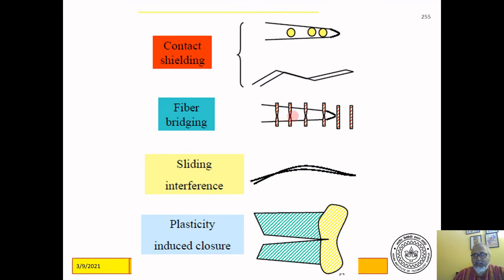If there are many of them all around, when a crack propagates, it has these fibers bridging the two crack surfaces, and thereby these crack surfaces are not exactly traction free surfaces. If you remove the fibers and draw the free body diagram, you have cracks with closing forces applied on them due to the extension of these fibers. As the crack opens, these fibers extend and they apply a closing force on the crack faces, which makes it a little difficult for the crack to open up, and thereby increases the GC.